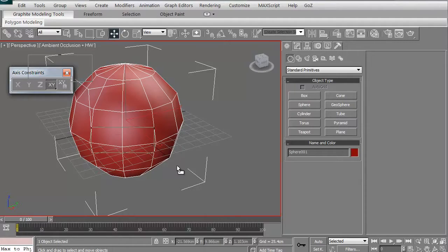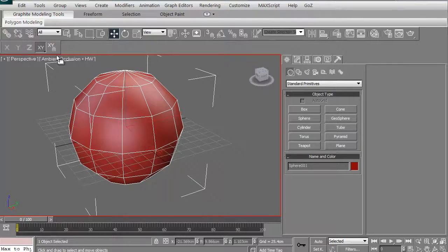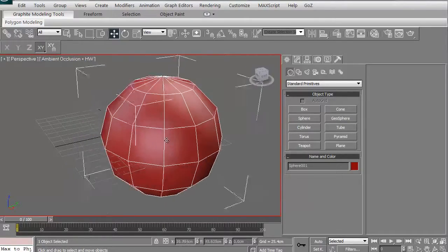Of course, this actually would then kind of interfere with your viewport as you're trying to deal with things. The fun thing is to dock this, we just have to left click, and we're just going to drag it up till we look like we're intersecting that main piece, and then just let go. It created the new dock, and when you restart 3D Studio Max, that will always be there for you from then on out. Okay, so that's a really fun thing to have.